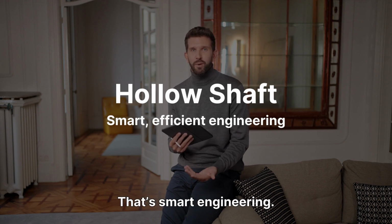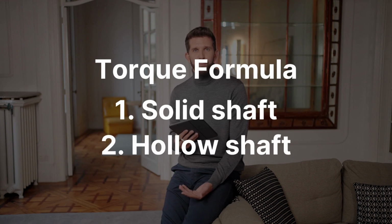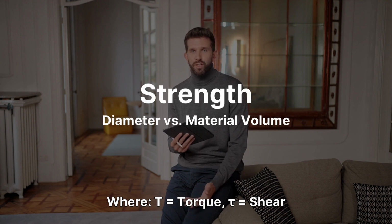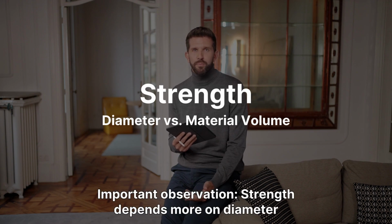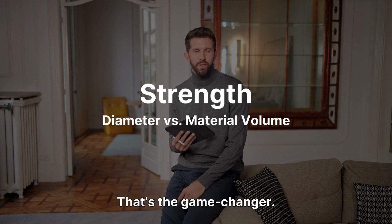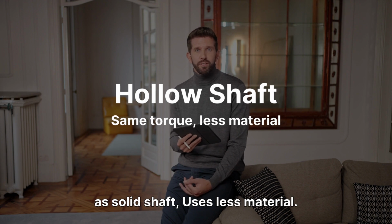That's smart engineering. Torque formula for solid shaft: T equals π τ D³ / 16. For hollow shaft, T equals π τ (D⁴ − d⁴) / (16 D), where T equals torque, tau equals shear stress, D equals outer diameter, d equals inner diameter. Important observation: strength depends more on diameter than material volume. That's the game changer. 1. Strength: hollow shaft can transmit same torque as solid shaft, uses less material.